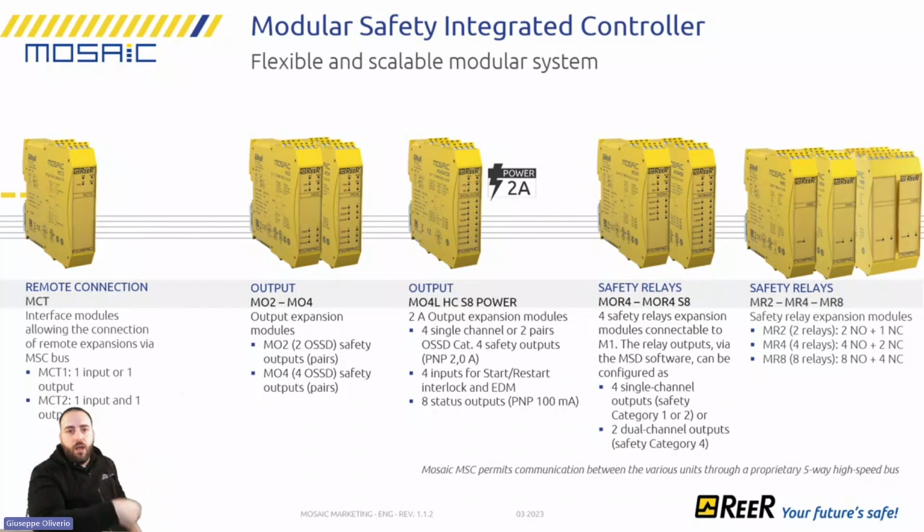For example, hydraulic valves, you can drive the hydraulic valves directly from this, so without using a relay in the middle. Or if you want to configure the logic of the relay, because these are OSSD outputs, and OSSD outputs, safety outputs are triggered, and maybe the valve is able to detect the trigger. You can also mount the relay module.